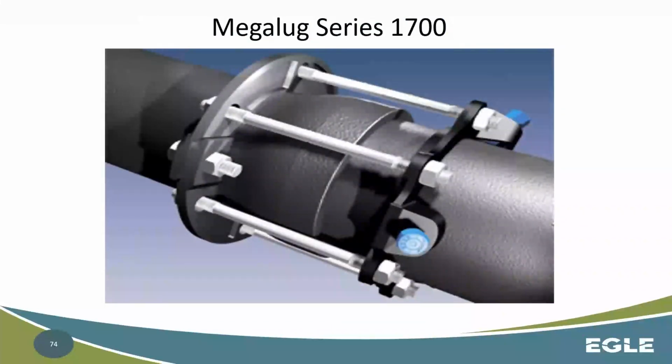This is obviously that mega lug. We've already kind of talked about this. You have these screws here that are actually pinching down into the pipe, keeping that in place. So again, just another method to dissipate some of that thrust. And obviously, maybe one of these won't work, so you should continue that down the line until all the thrust is dissipated in that length, similar to what we talked about earlier with extending that length of water main.